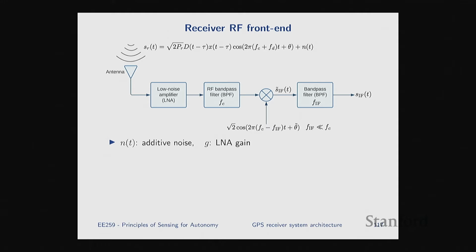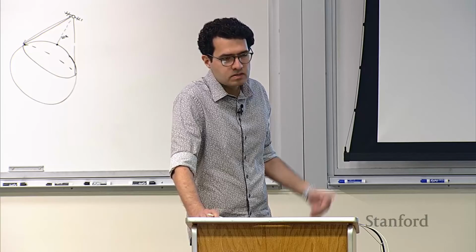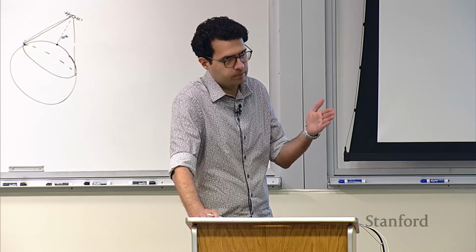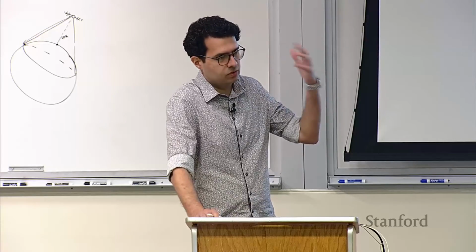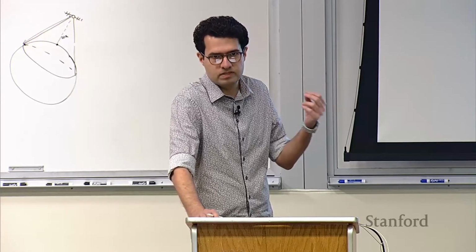And the reason is, usually if you look at the noise spectrum, the closer you get to DC, things get more noisy, right? There's the 1 over f noise. There's other effects that make the DC portion of the spectrum pretty noisy. So you want to delay bringing your signal down to that part of the spectrum until the digital domain, because then you don't mix all these analog low frequency noises into your signal.